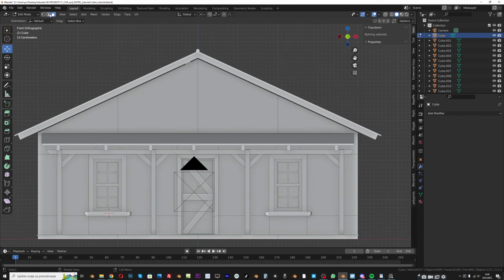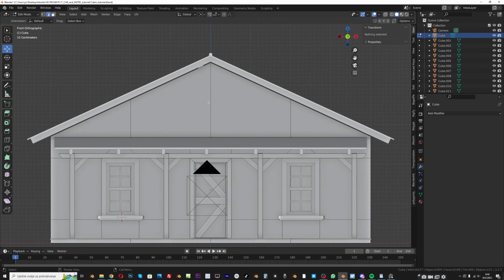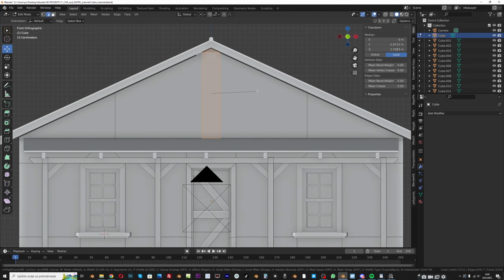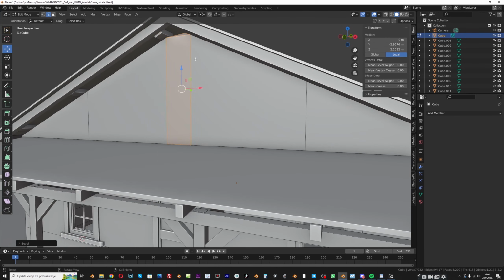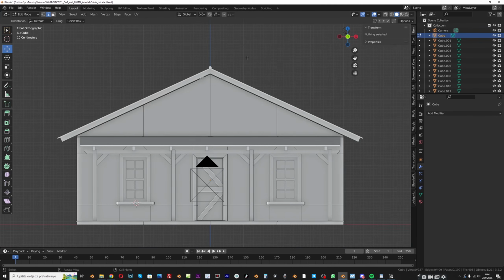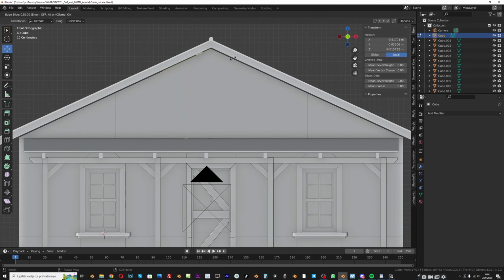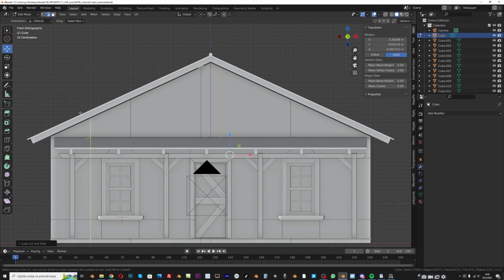go to edit mode and edge select, and you can see if we grab this edge and go with Ctrl B, we have little problem here. So I will add another loop cut, one here and on right side also. And we need loop cut on X axis, so Ctrl R. And if I press now SZ0 to scale this on Z axis, we get this problem here. So I will go with Ctrl R.